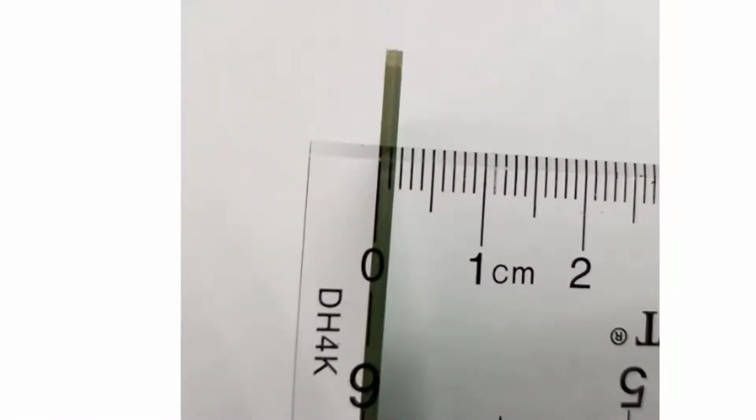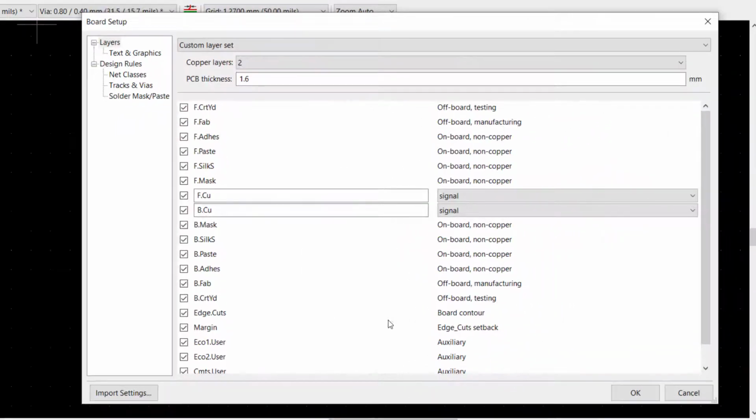And we can set the PCB thickness of the board. I wasn't sure on the thickness, so I went and measured the board I'm going to be using. Looks like about 1.5 millimeters thick. I looked up on the internet standard board thicknesses, and it was reported in several places as 1.57 millimeters thick or 1.6 millimeters. So this looks correct for my board that I'm going to be using.